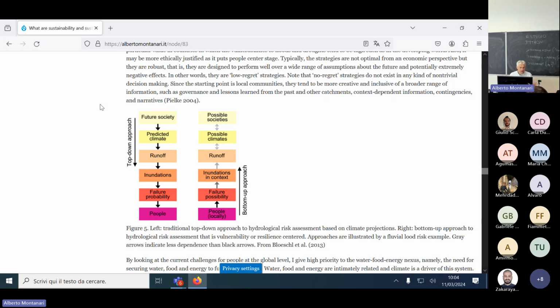The model is uncertain, I'm aware of that. So if I get a storage for the dam of, say, 10, in order to make sure that I get protected against uncertainty, I suggest a storage of 15, and this is a safety factor of 1.5, which is the safety factor that is normally adopted in engineering. This is the usual way of engineers to cope with uncertainty, and it's very classical.